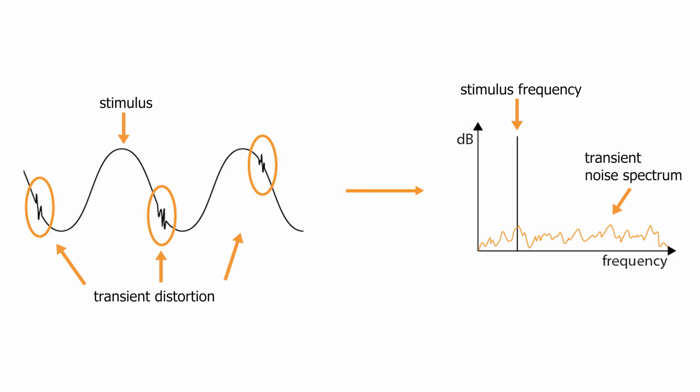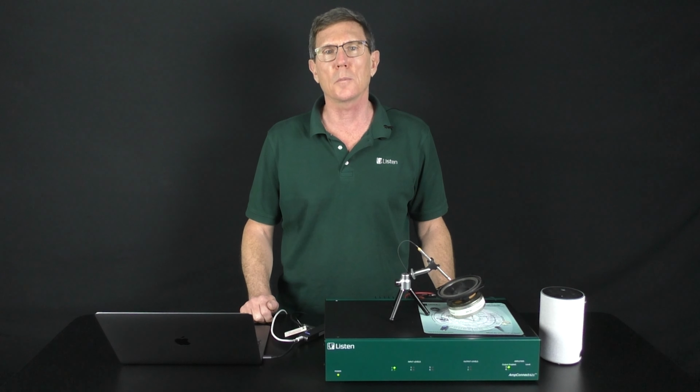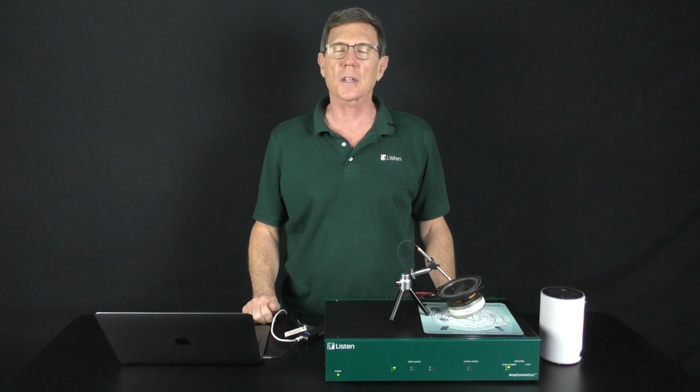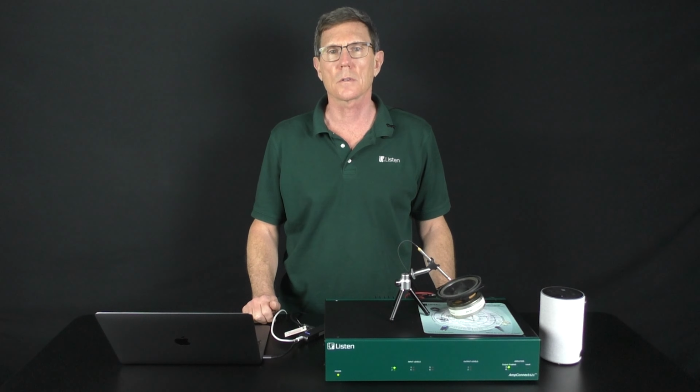This is different from periodic distortion, where the defects would show up as a series of vertical lines at the harmonics. So although periodic or rub and buzz distortion is best identified by the frequency at which it occurs, transient distortion is best identified at the time the transient occurred. There are measurement methods that actually measure loose particles and periodic distortion together, but we recommend measuring them separately as they are caused by completely different mechanisms.